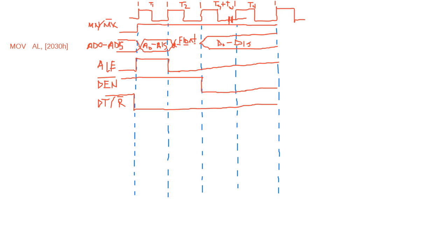All right, so what are the other signals? Is it memory or input output related? As it is a memory related operation, it should be a high signal all the time. And if it is an input output related operation, then make it low for the whole time.